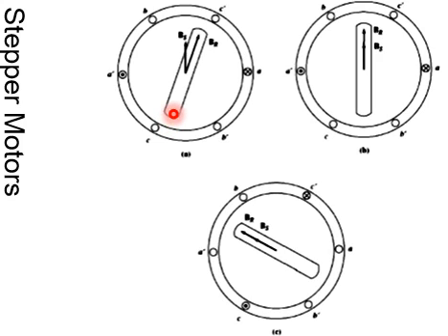It can be seen from this diagram that at the first pulse A is VDC and B, C are 0, then the A winding, A bar is this loop, and the magnetic field would be something like this.